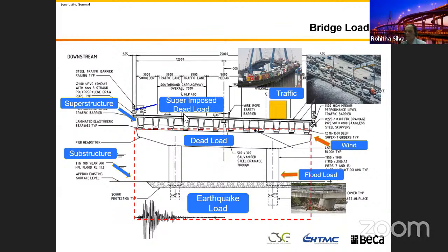And then we talked about the bridges being long and slender, very heavy structures, with dead load. In addition to that, we put what we call the superimposed dead load. After we place the deck, after the bridge becomes composite, we apply the load on top of that, like a wearing course, barriers, lighting, improved drainage, and all miscellaneous stuff on the bridge deck. We call it superimposed dead load, like a wearing surface. For example, you put a 70 millimeter thick wearing course, but over time, 10-15 years later, it will be reduced to 30-40 mm. Then you have to resurface.